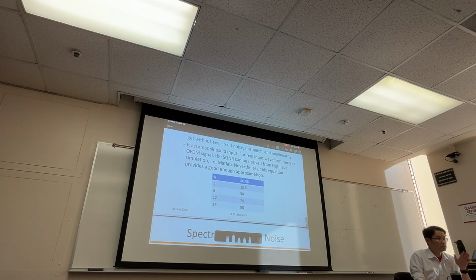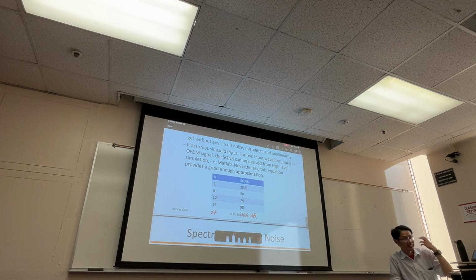People do build ADCs above 16-bit, just so you know, especially for audio. So 20-ish bits, 24 bits is 146 dB. Remember I talked about the human ear being very sensitive. So indeed, people build 20-ish bit ADCs.